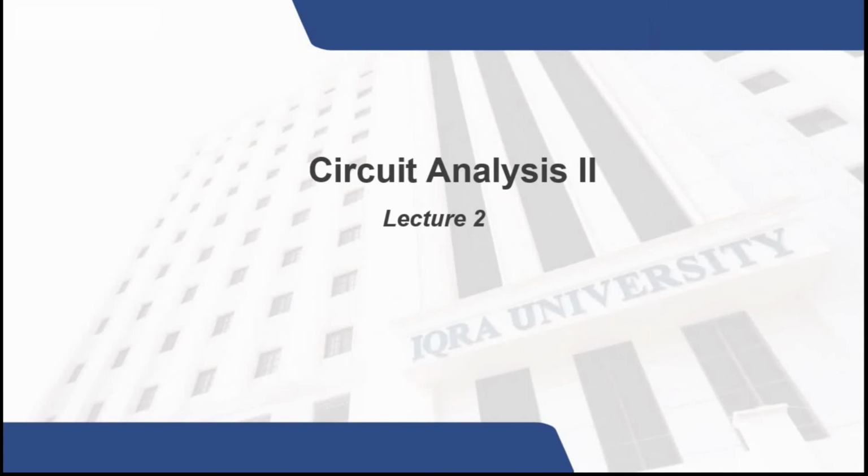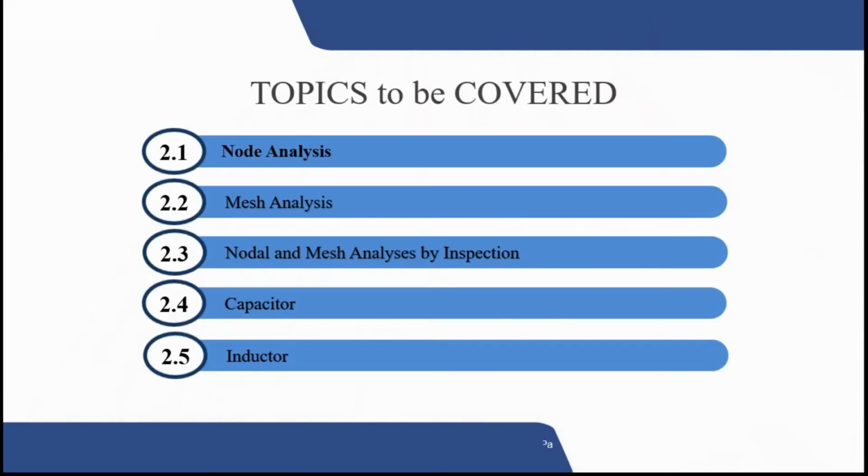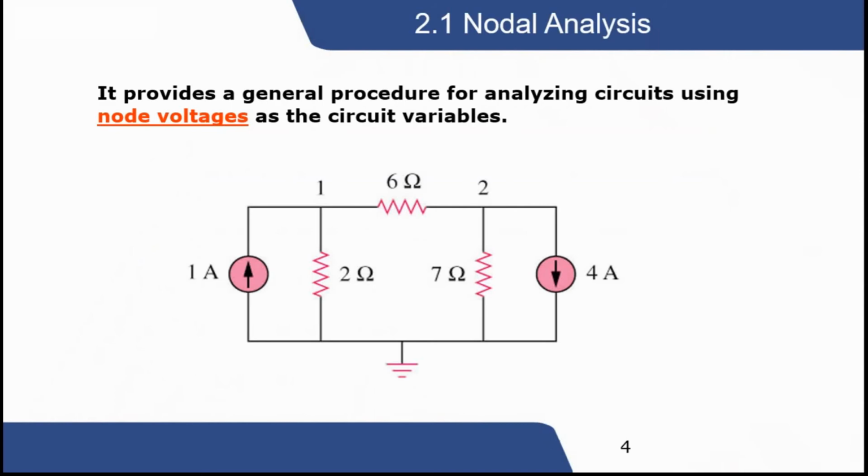In this lecture, we will study nodal analysis, mesh analysis, nodal and mesh analysis by inspection, capacitor, and inductor. Nodal analysis provides a general procedure for analyzing a circuit using node voltages as the circuit variable. So in nodal analysis, you must understand that the main variable is the important thing. The main variable is node voltage.